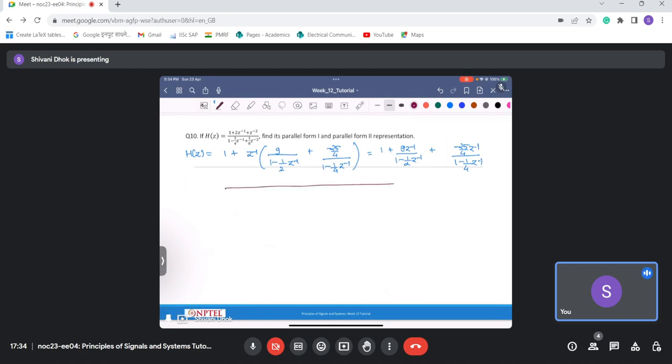So what I have is this x[n], which is going directly to my output. Then this is the first system that I need to represent. So here this x[n] gets added with the delayed and scaled version, and this resultant thing gets amplified by a factor of 9.